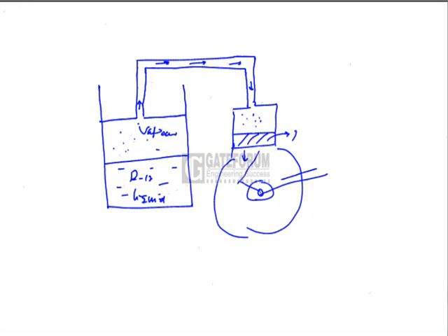This is piston. With the help of the piston, the vapor is drawn the moment it is formed over the surface of the liquid. Thereby, the pressure is maintained less than atmospheric pressure over the surface of the R12. Now, if you keep the thermometer, the temperature may be even minus 30 degrees centigrade.